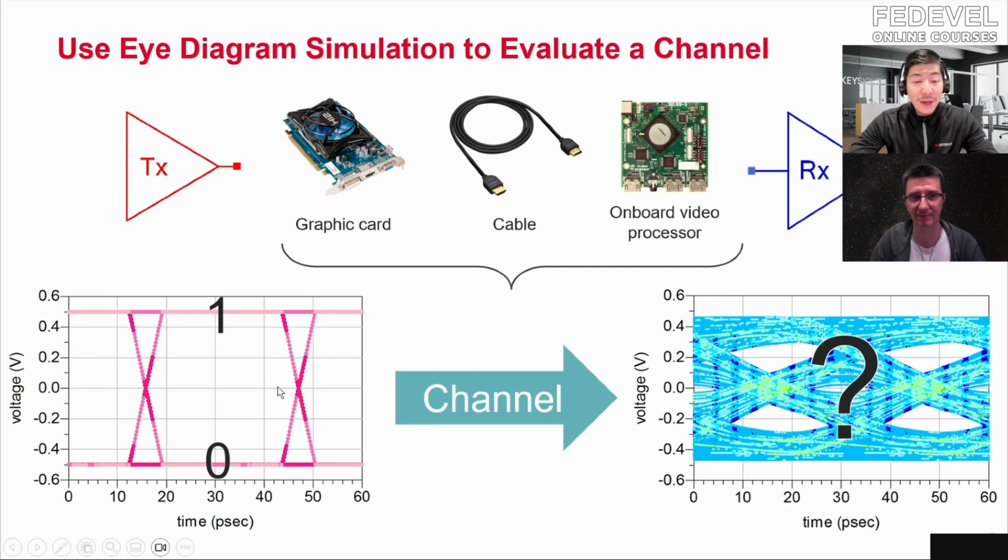Typically, you will have an eye mask in the middle to label it as a keep out. So I'm marking it on the left here. Usually there will be some sort of a diamond or a shape in the middle. If anything were to come inside of this eye mask, then you'll be violating the eye mask, and your eye will be closed. That's one of the metrics that we use. Does this mean that some of the signals were out of specifications? Yes, exactly. Oh, cool, perfect.